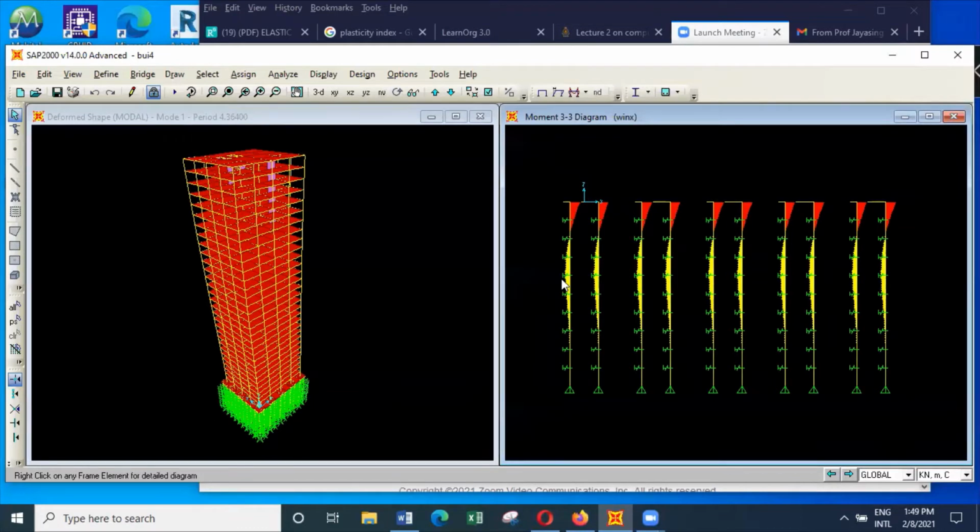And because of that reason, the maximum stress on the pile will act as if it is fixed at this particular point, and the maximum stress on the pile will act here. But here also you can get some bending moment, and here also you can get some bending moment, and the bending moments on those two locations should be checked to see whether they are excessive. But in most instances you will find that because we are having 4 piles, these moments cannot be excessive.